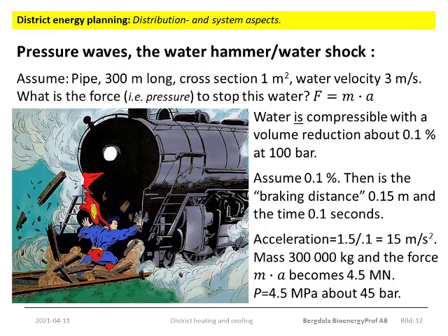Let's just do an oversimplified treatment in which we assume a completely rigid tube in which water is flowing at 3 meters per second. The tube is 300 meters long and has a cross-section of 1 square meter. So what will be the force we have to apply to bring this mass of water to a full stop? And since we know the cross-section, we will transfer that to a pressure. Since the tube is completely rigid, we have to estimate the braking distance by aid of data for water.